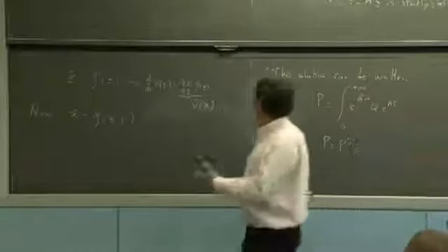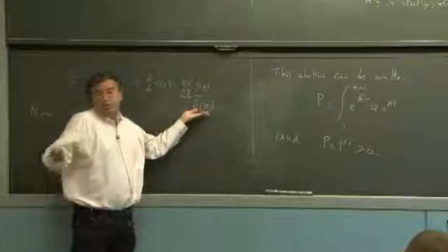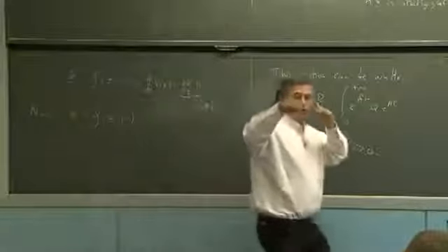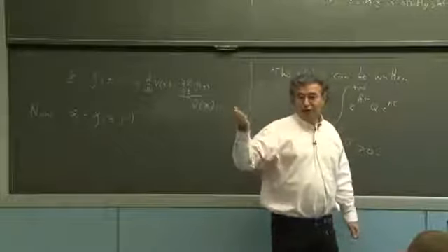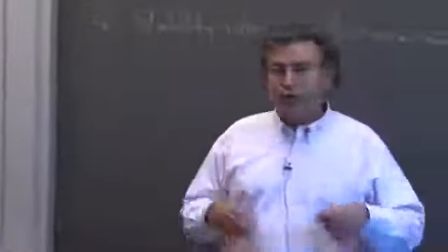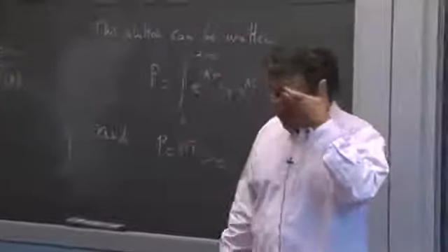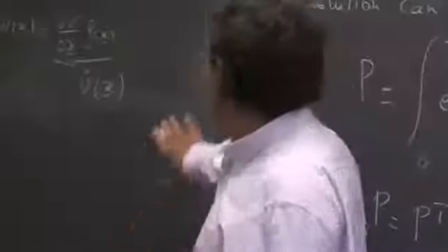Now, of course, you can see immediately that if you have f of x and t, it's not going to be V dot of x. It's going to be V dot of x and t. Which means that at a particular point in the state space, you won't be able to give a velocity in V unless you know time as well. So the geometry is going to become more complicated, or less natural. So that's one way to see it, from the basic proofs of the fundamental Lyapunov theorems. We know that we relied heavily on this.